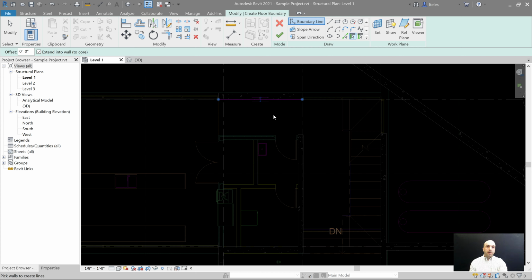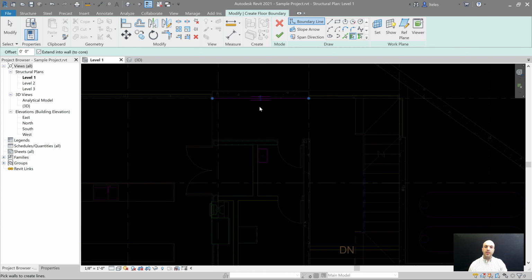That wall will already be in place. It'll already be poured and shot. Remember, we're shotcrete. It will already be there by the time this floor gets poured. So when we go to pour this floor, it needs to go to the inside. It needs to wrap around that wall. So I'm being very literal in my selection. But the beauty of picking walls is that later on, if this design changes and the architect wants to make this corridor a little bit larger, once you start moving that wall, your floor edge will move with it. So it's also good to know the behaviors that Revit gives you.